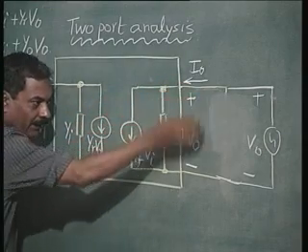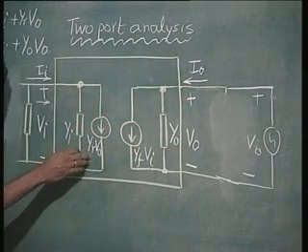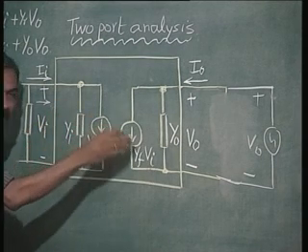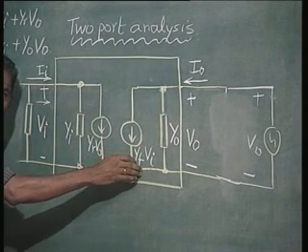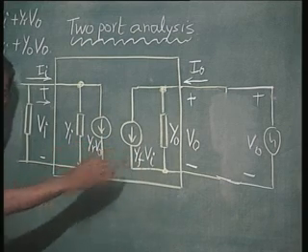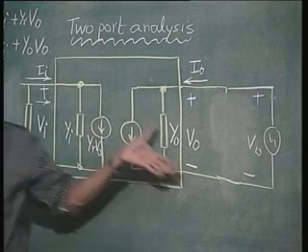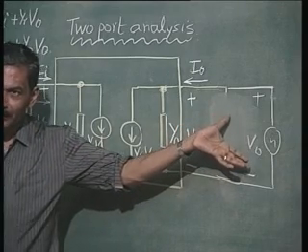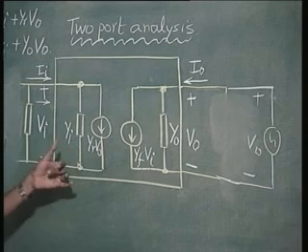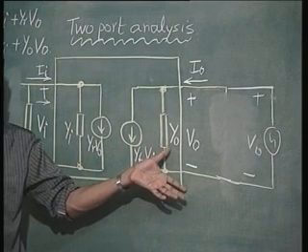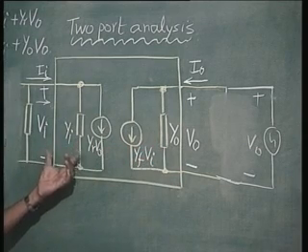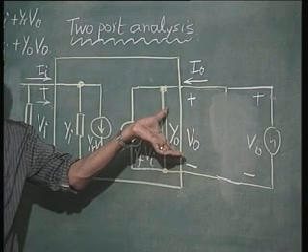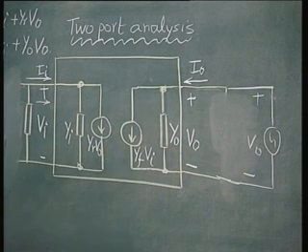If something is applied at the output, this YR should be present, so that it conveys it to the input, and this input is in turn bringing it to the output. So both YR and YF should be present in order to feel something at the output, when I am exciting at the output. If YR is 0, then nothing is transferred from input to output. So this impedance is going to remain as the output impedance. Let us now see what it is.